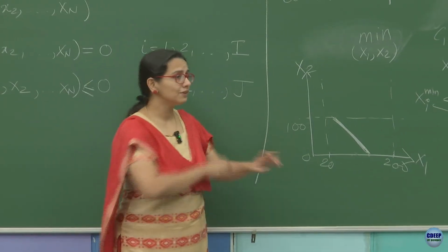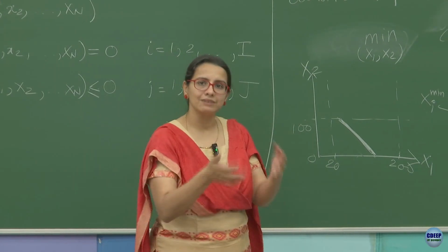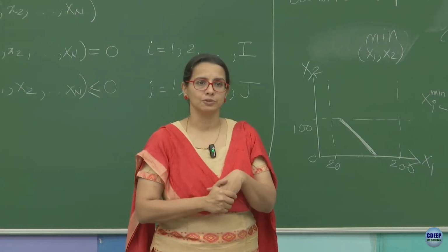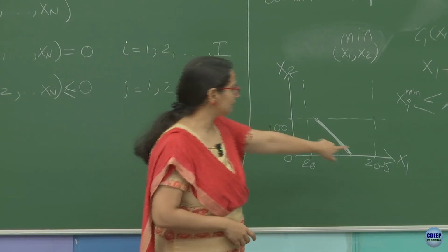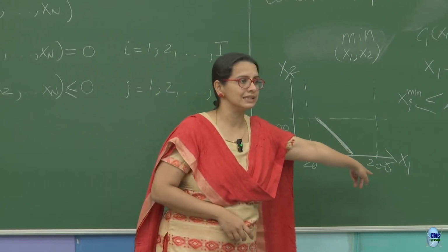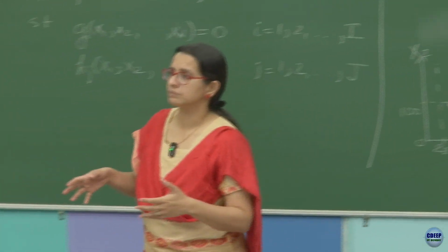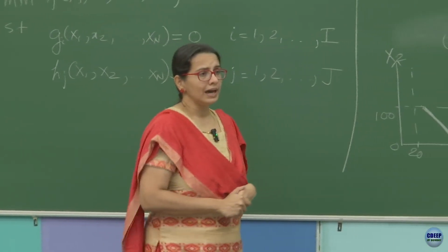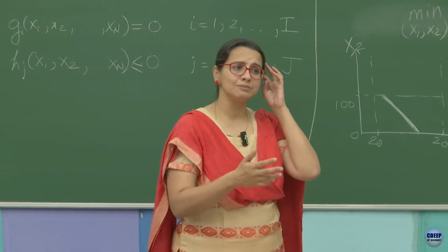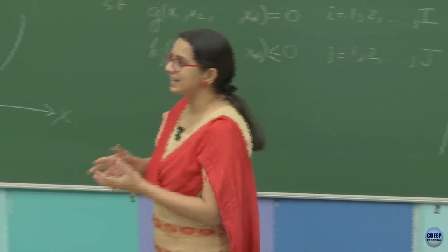No. Even if I was to run both generators at their maximum, I can never meet a demand of 350 megawatts. The maximum capacity of one generator is 100. The maximum capacity of another generator is 200. What does that make my problem? Infeasible, right? If you have an infeasibility in your constraints, then that means basically you can't go ahead and optimize anything on it.